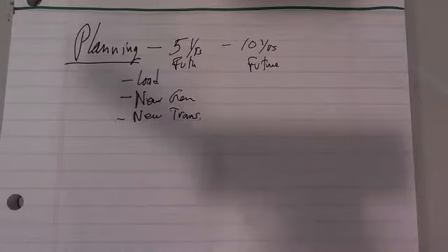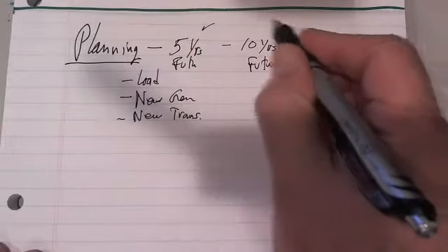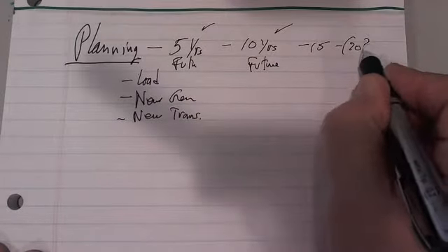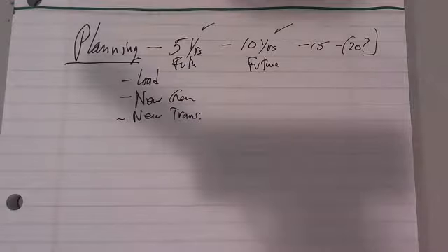Obviously, you need new distribution, but that's just dictated by where the load is. And you don't usually build distribution too far out because it's expensive. If somebody starts a housing development, you want to put the distribution in just about the time they start construction or a little bit before. But transmission might take 5 years, 10 years, 15. We can even put 20 with a question mark. Well, you want to look way out into the future.